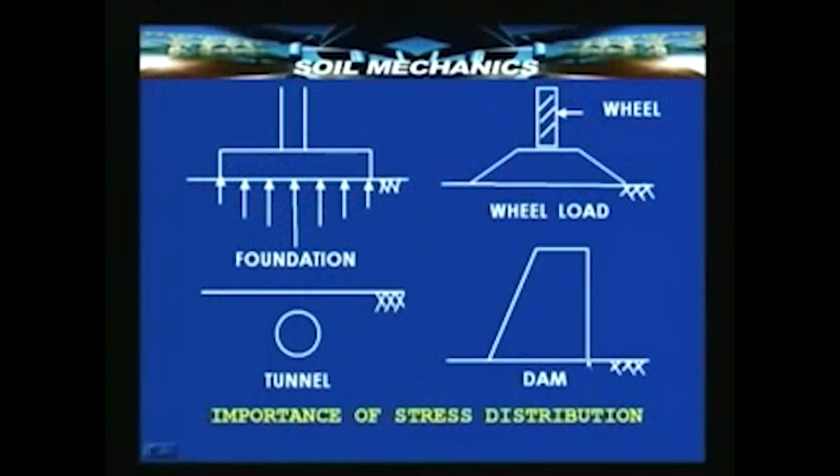Take a look at this diagram, the diagram of a dam. This is a typical dam. This imposes stresses on its foundation. The shape of the dam, the water that is stored on one side, all these are going to impose loads on the foundation. The loads are not going to be uniform, and we need to know how the stresses are going to be distributed inside this foundation.